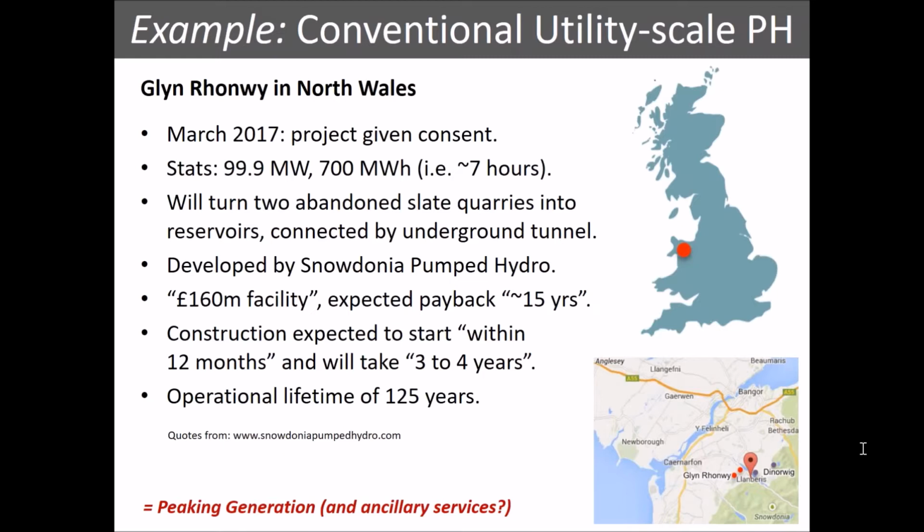pumped hydro scheme in 30 years, I think, here in the UK to be given consent for construction. Again, similar size, 99.9 megawatts, which is interesting, so about 100 megawatts. Much longer time frames, 7 hours of storage. Again, it's using abandoned quarries in this case, so 2 reservoirs, you pump water up and down between them. Much different business prospect. So they're expecting payback over 15 years. Now, battery developers I've talked to are talking more in timescales of a few years.